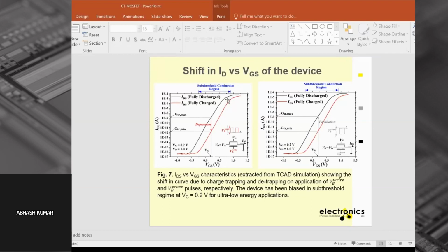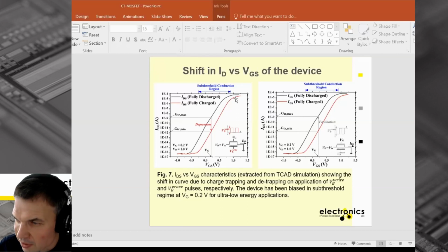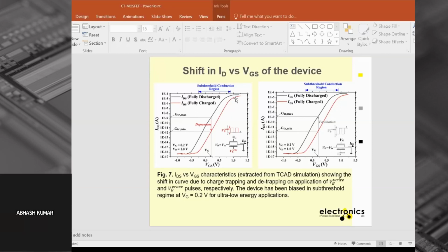So this is the log plot. The exponential region is shown in the linear. This is the subthreshold conduction region. But at the top should be somewhere saturation, since there is the output characteristic. No, sir, it's not the saturation. Actually, we know that there is a V square type of dependence, meaning (VGS minus VTH) whole square dependence.